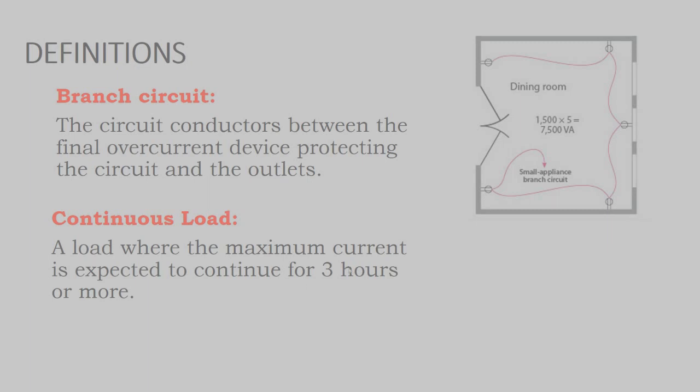But they're also referred to in code as something completely different. So you could have an AC branch circuit on a microinverter array that would be a solar inverter output circuit. Or you would have a DC string running between your array and the inverter on the side of the building, and that would still be a DC string. It would also be a different circuit category, the photovoltaic array output circuit. We'll get into that tomorrow.